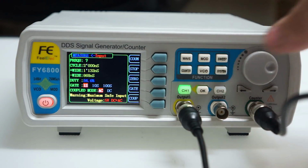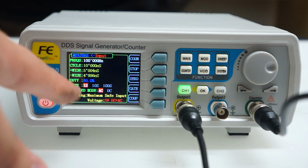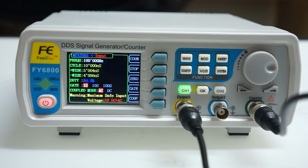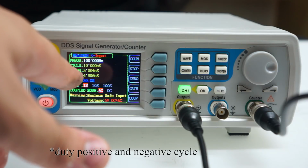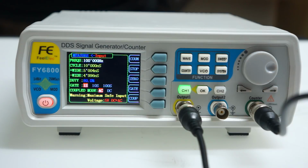Let's go to counter, and there we go, 100 kilohertz at the gate of 1 second. If we change it to 10 seconds, it does the averaging within 10 seconds of the signal. You can see the rise and the fall time, as well as the cycle and the duty cycle, which may be hard to see on the camera because I can see it on the device itself. I'm looking from an angle from above and it's quite dark blue.